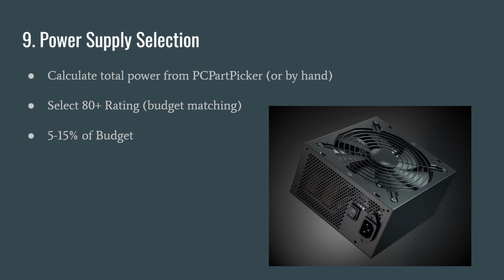And then, you're going to want to buy the power supply that is in that range of power. So a power supply usually will say, oh, I'm an 850 watt power supply. I'm a 750 watt, 650 watt, something like that. And don't buy right up to it. Like if you calculate it and you're at like 643, don't buy a 650 power supply. Just buy a 750. Buy a good 100 over maybe, just to be safe, I would say.